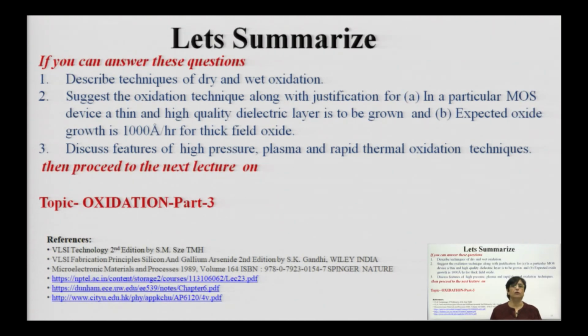So, you have different techniques that we have studied. We have studied wet and dry oxidation techniques, then specialized techniques which include plasma oxidation, where we create plasma by DC or RF heating. Those oxidizing species are made to flow over the surface of the silicon and they react, and a controlled environment is presented by controlling pressure and temperature, so the oxidation happens at a lower temperature. Another method we have seen is thermally grown oxide, like rapid thermal oxidation, and this is how we have summarized the different methods of oxidation in this lecture.